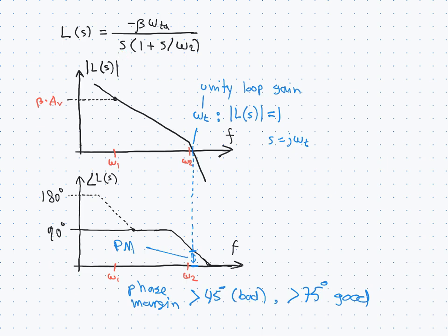And then we subtract 90 from the 180, this is the phase we have here. And then the phase from that is going to be subtracted from what we have left, so 90. And this is then the phase margin, like this, where the angle of this complex number is easy to find because it sits in the first quadrant. So this is just the inverse tangent of that ratio there.